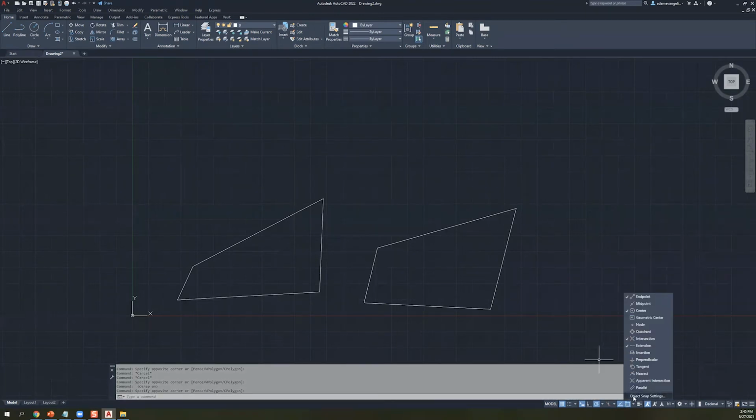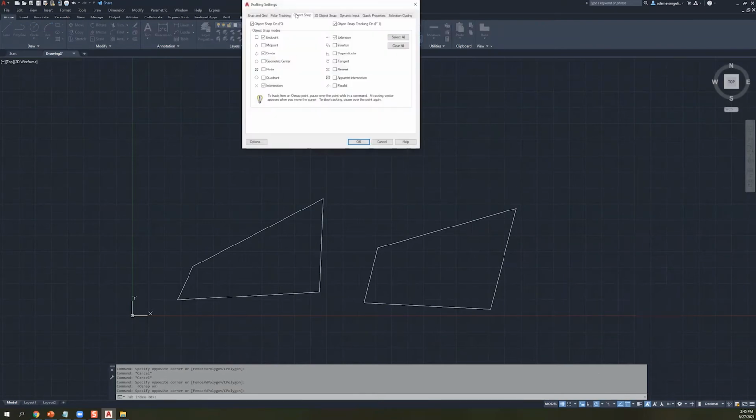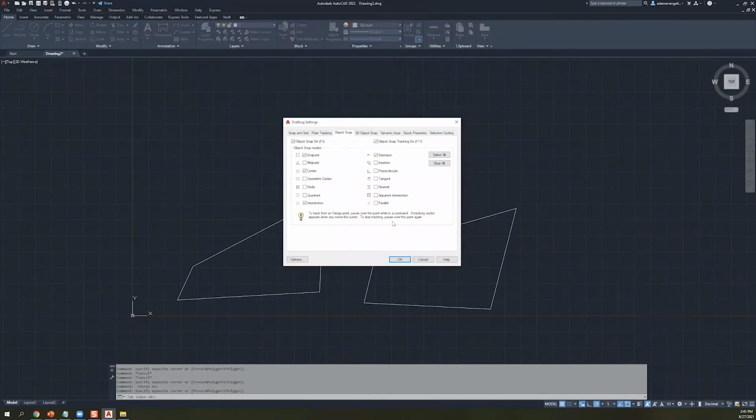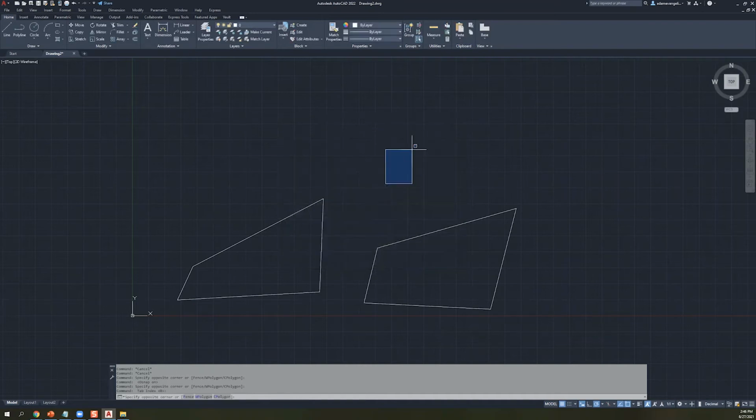And if I right click and I go to object snap settings, right, here we are now. You can actually take a look at the different toggles that are available over here, right? So same exact information as what we saw previously, but you could just go through and toggle all the bits that you want. Midpoint's a popular one, for example. Quadrant's really helpful. Perpendicular, we'll see. Tangents, let's see. And let's just go with that for now. Even this is honestly more than you probably want.